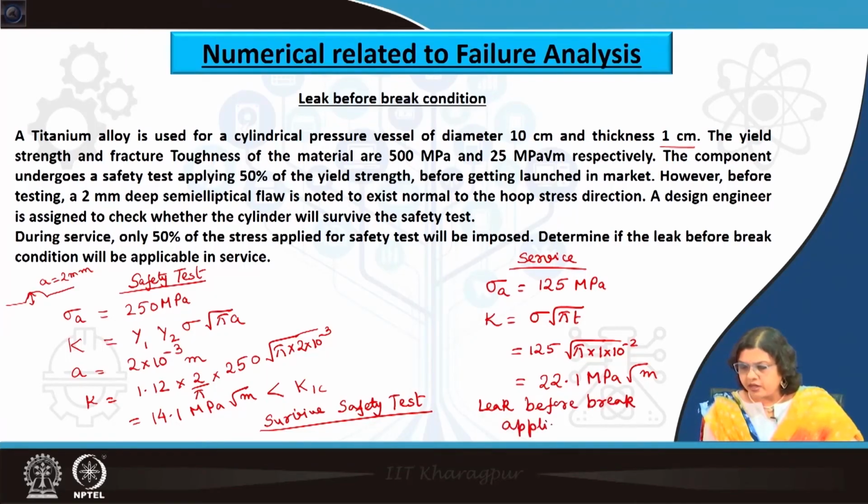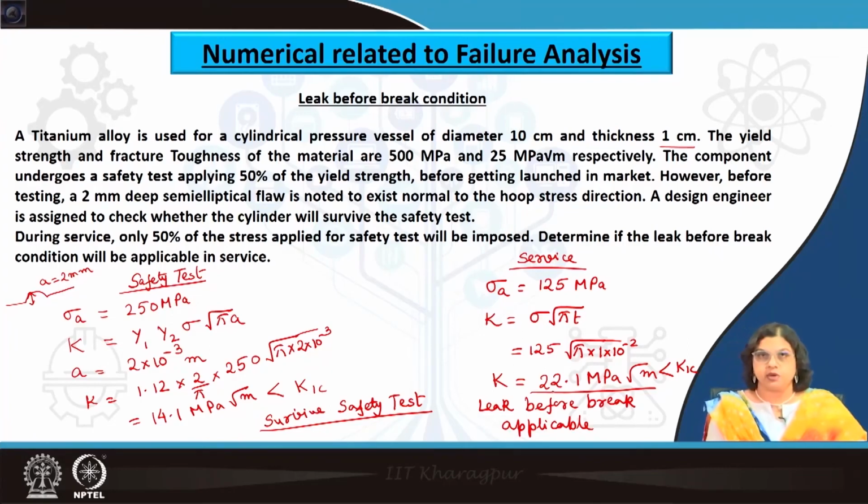because this value that is generated is less than the K1C. So, it will fracture at the point of contact, at the leakage point, that will lead to the leakage, but the margin is very low because K1C is only 25 MPa and we are getting a value of 22 MPa. The margin is really close, and that should also be considered while using this in service.